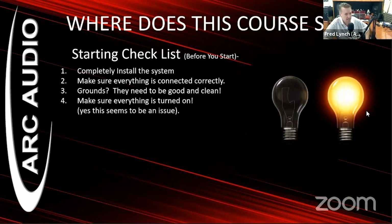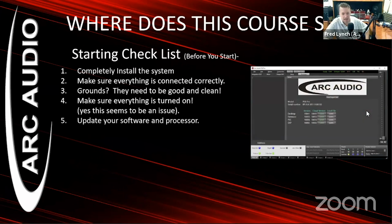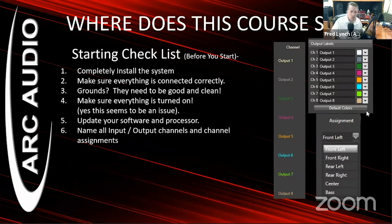And this one seems so simple, but make sure everything is turned on. I can tell you a story after this is all over with on that one. And the other one is make sure you update your software and processor. We're going to go over that hands-on here at the end, but this is a big deal, especially if you're running a PS8, not a PS8 Pro or one of the Pro-Series DSPs, because there were no automated tools like in the new Pro-Series DSP that tells you if you're out of range of an update between the desktop software, the firmware, the DSP code, or the PSC. And you definitely need to make sure that you're up to date on anything PS8-wise.